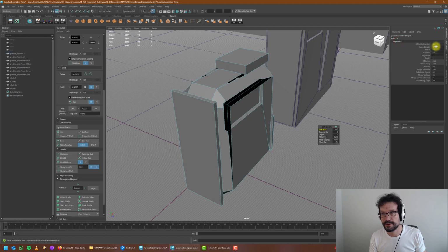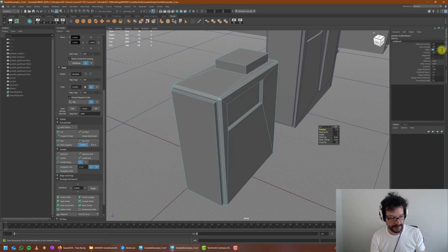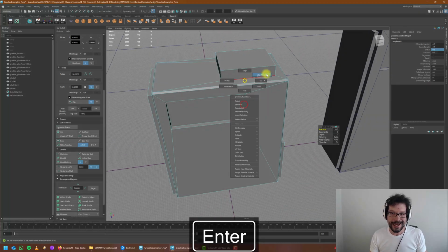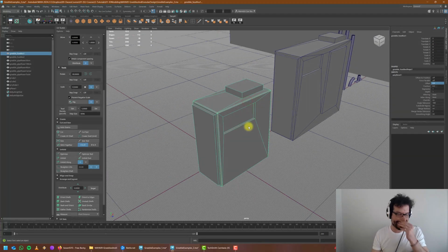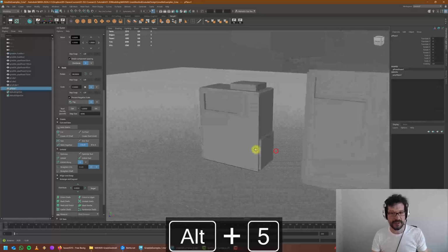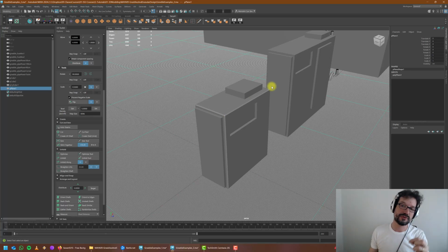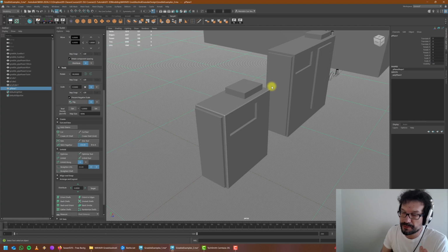And obviously we have to say this, you can even put smaller bevels on them. This will start to read better because these edges will start catching highlights, which is what they're supposed to do in the first place. But you can easily do this with normal maps as well with the bake trim approach. But you can combine the two of them as well. But I highly suggest the bake trim approach.